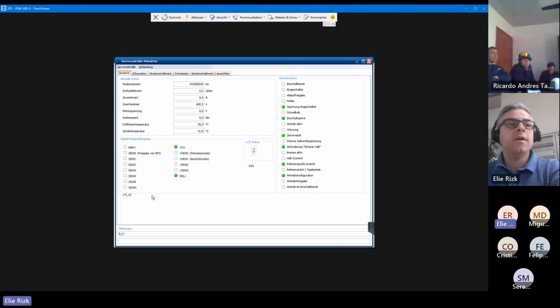So you can come here and see if you have any error. Here we show the error that is generated by the inverter. Sometimes you have here E squared T. This means a high temperature, or high current for a long time. This can help you understand a little bit what is going on.